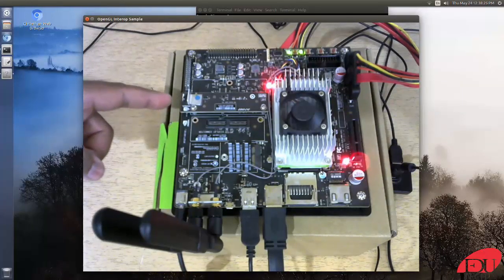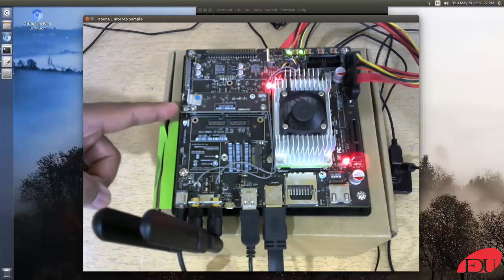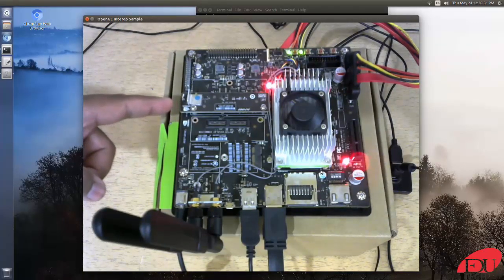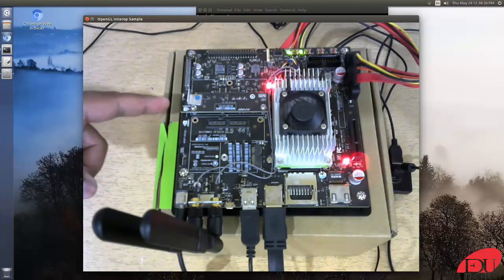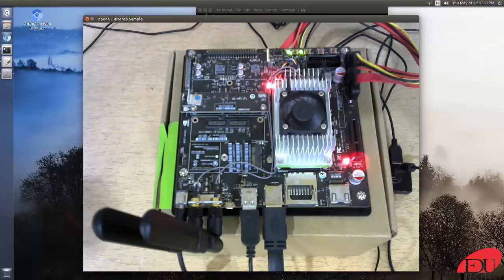Okay, so you can connect sensors through it or any sort of input or output devices. And the most important thing, this board comes with a 5 megapixel fixed focus camera, which is directly connected to the board itself using the CSI MIPI interface. And the benefit of this is there is a language supported on this board which is called OpenVX, which is similar to OpenCV, but it's more on hardware processing. And since this camera is on board, you can take benefit of hardware image processing.